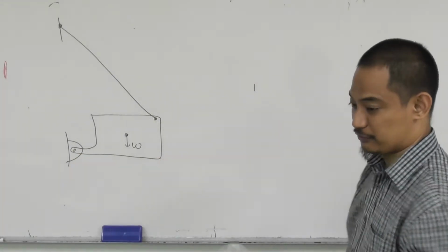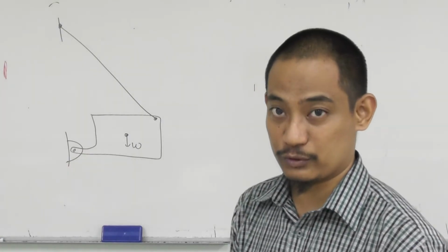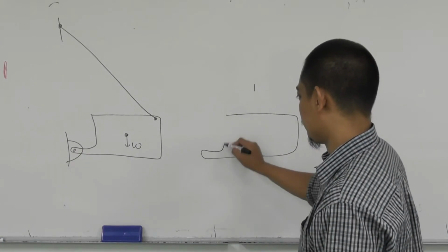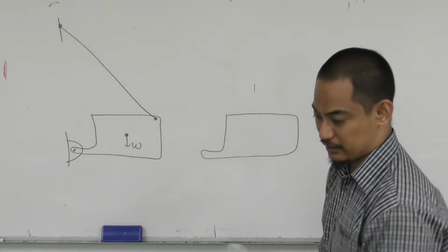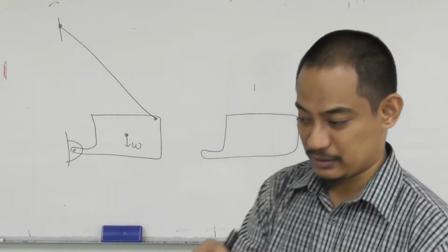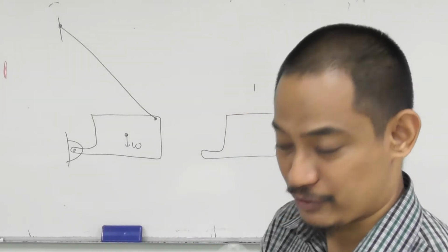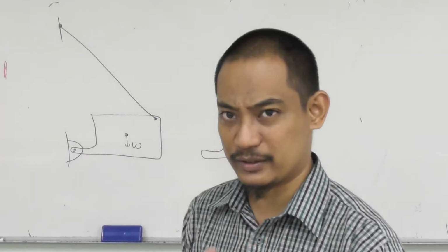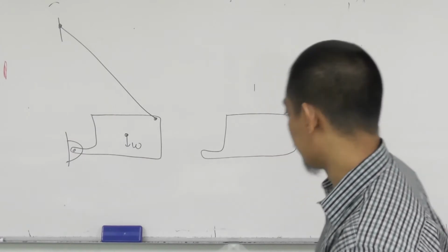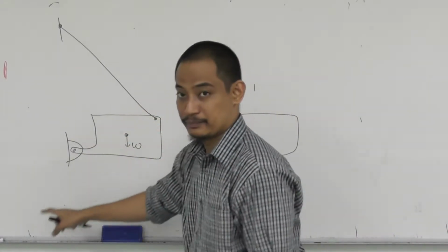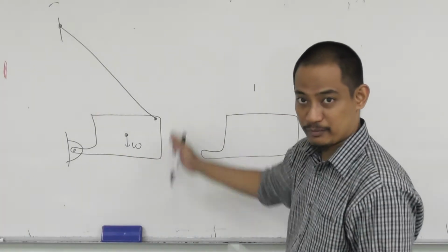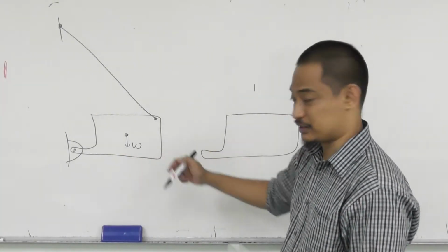If you want to draw the free body diagram, and you need to if you want to solve it, then the first step is to draw the outline shape, something like that. And then you have to put in all the dimensions. Again, I'm focusing just on the forces, so I'm not drawing the dimensions, but in an actual free body diagram you have to have the dimensions. Now the pin prevents this movement and this movement, but it allows rotation, right?